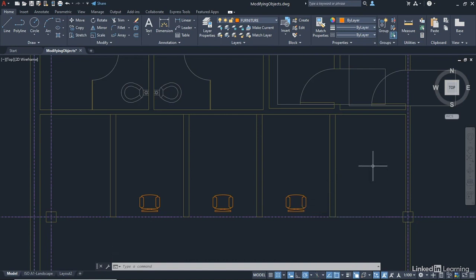Once you've got all of your drafting settings ready to go, we're going to go up to the line command on the draw panel. There's the line command there. I'm going to come into the drawing area. Now, we're not going to select our first point. We're going to hover over it like that. It's that intersection there where the internal wall meets the main wall. As we come down, you'll see that we get an extension distance. Can you see that? What I want you to do there is select a distance of 900 and press enter.